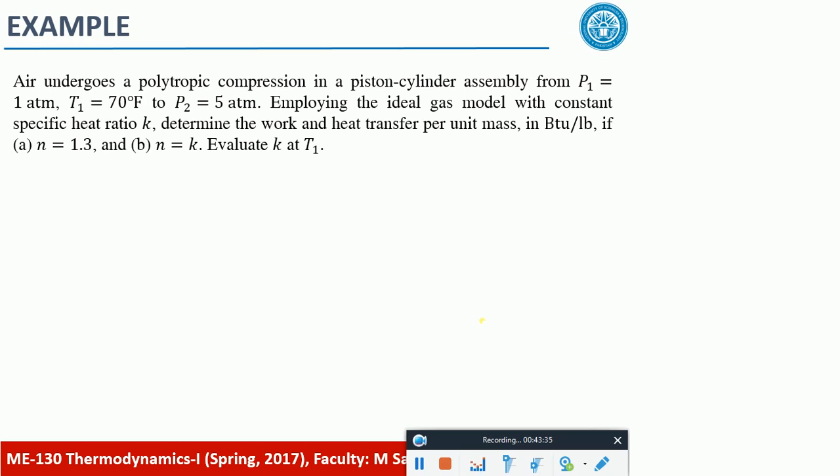Do you know any relationship between work, energy? What is that? That is the first law of thermodynamics, right? In the first law of thermodynamics, what kind of energies were involved on the left hand side? That was kinetic energy, potential energy, and internal energy. Generally we do not talk of potential energy and internal energy separately if we are talking about a gas. Generally we talk about those terms when we deal with something rigid. Otherwise for gases everything is incorporated into internal energy. So then again m into u2 minus u1, you know that.